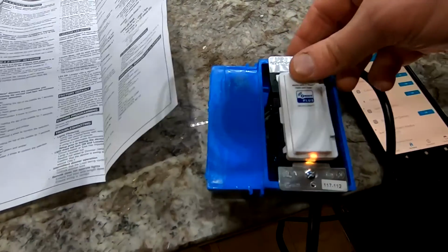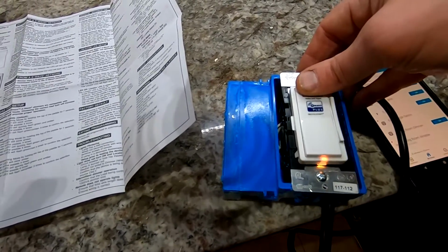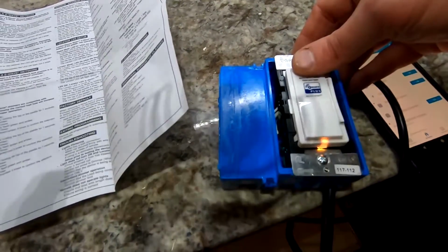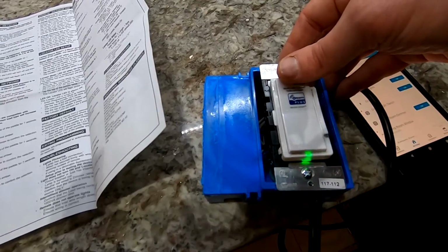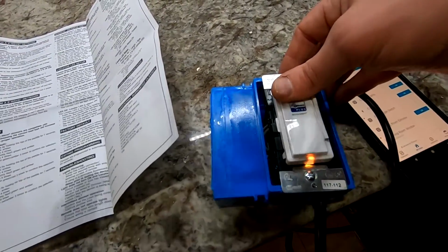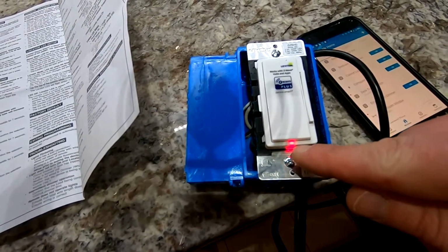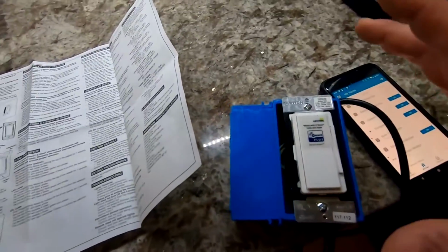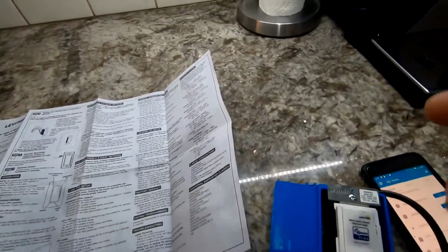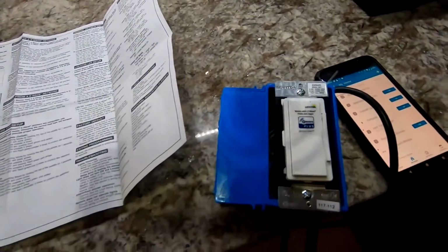Okay, now to get into LED load, it's 4 clicks. 1, 2, 3, 4. It starts blinking green and amber. Now to tell it LED, we're going to say 5 times. 1, 2, 3, 4, 5. It'll be green and red blinking down there for a couple. Turn off. Now it knows my load is an LED load. Okay, the under cabinet lights for me are LED. If yours are something else, you can adjust that based on the settings, whether it's CFL or incandescent.